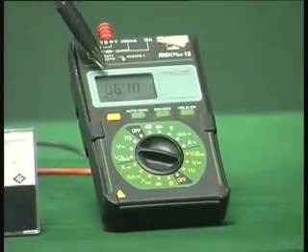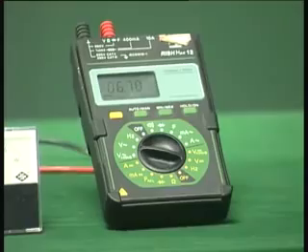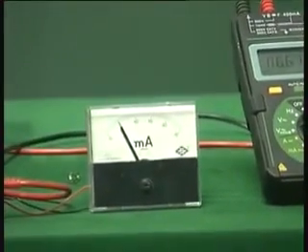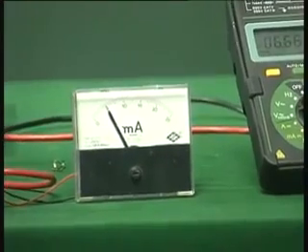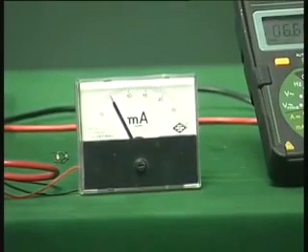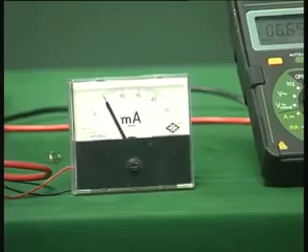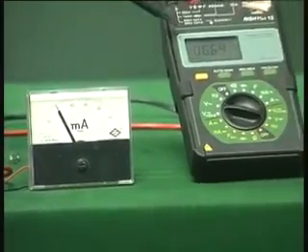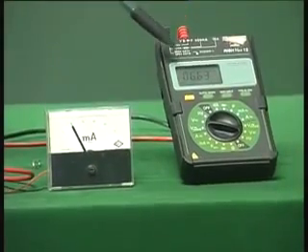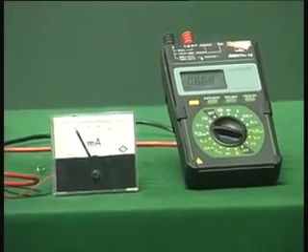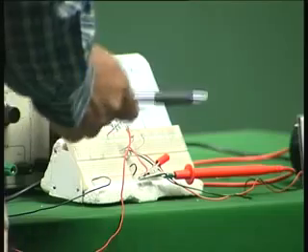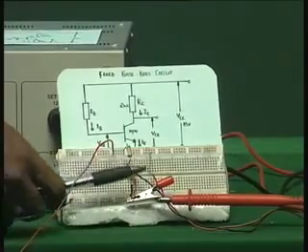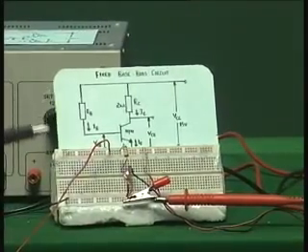We wanted to have around 6 volts, it is around 6.7, and you can see the current is about 5 milliamperes. So the same thing which we designed, we have implemented there. You find the voltage and the current are very close. There are some changes. For example, instead of 6 volts, you are getting about 6.6 or so, and that is because these resistors have got some tolerances. As we all know, it may not be exactly 820 kilo ohms, and this 2 kilo ohm may not be exactly 2 kilo ohm, etc.